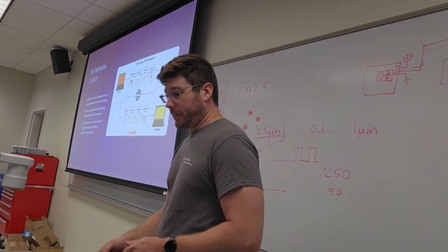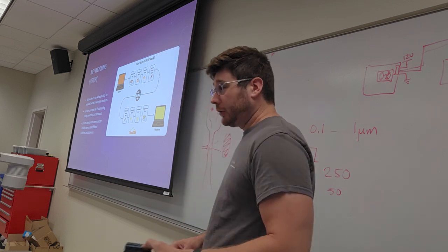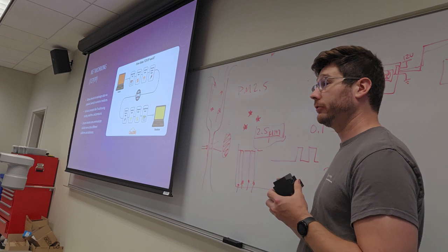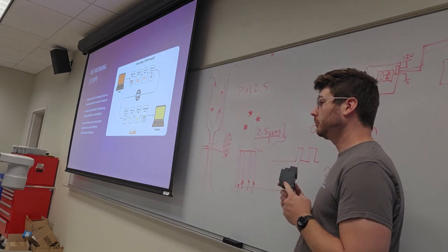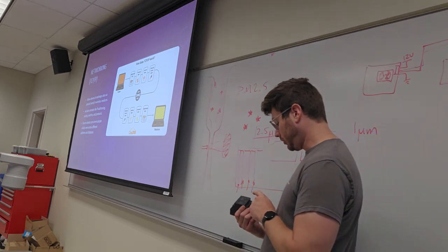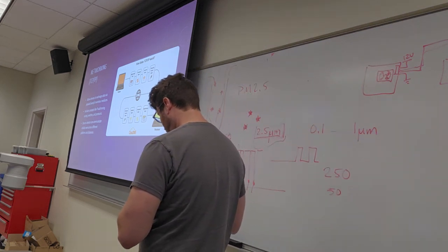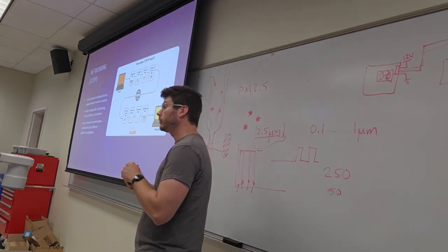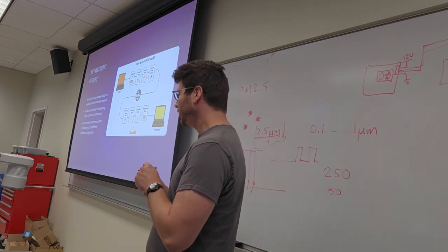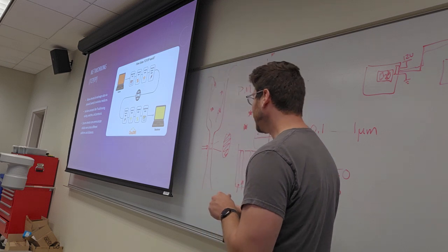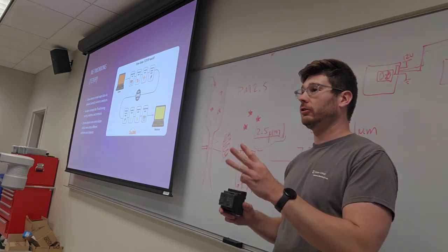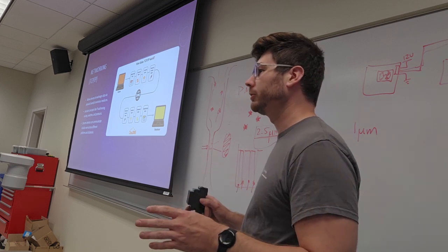The great thing about modern PLCs is that it's fairly easy to get them to talk to each other. Literally, they have Ethernet ports in them, right? You can get them all on the same network, all talking to each other through Modbus, through that port, or they can all join through with these 3 wires. Again, those 3 wires get you on the Modbus bus, okay? And that allows communication between up to 255 different devices that are all sharing those 3 wires. And that's really just as simple as that.